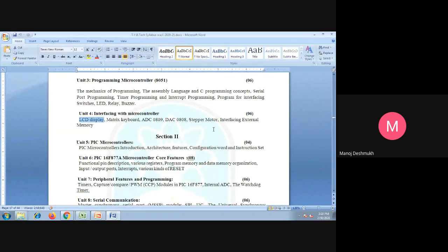which is already stored, like we have seen, the message we transmitted, such as "good morning". Each individual character is already stored or loaded in a memory location starting from, suppose, 4000H onwards. In that case, this memory acts as an input and provides output to the LCD. And if we are going to store the data which is received when serial communication is completed, at that time memory acts as a storing device.